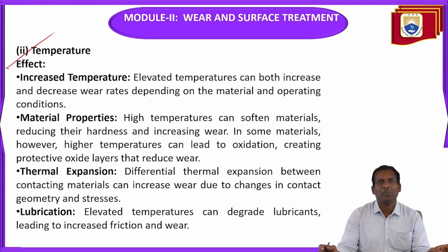Similarly, material properties: high temperatures can soften materials, reducing their hardness and increasing wear. In some materials, however, higher temperatures can lead to oxidation, creating protective oxide layers that reduce wear.